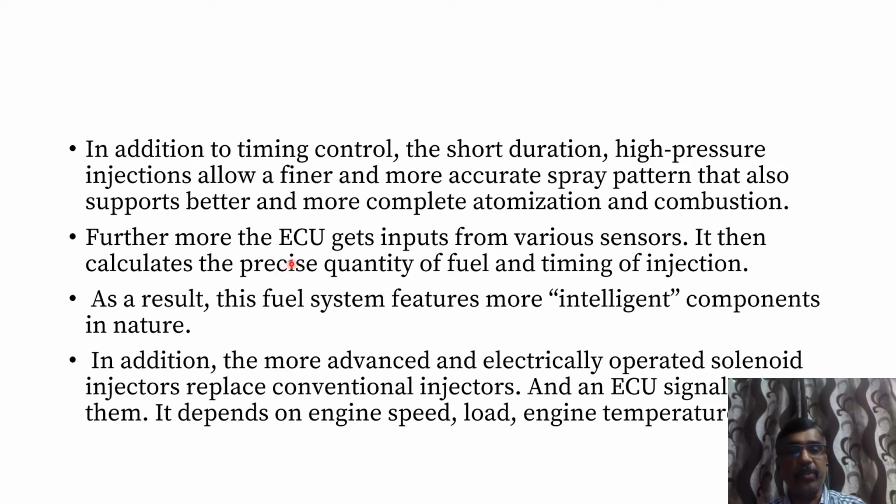Furthermore, the role of the ECU is to get inputs from various sensors, and it then calculates the precise quantity of fuel and the timing of the injections. The sensors are placed wherever the parameters need to be controlled, like the accelerator. Whether we are increasing or decreasing the accelerator, the sensors sense it and accordingly it allows.